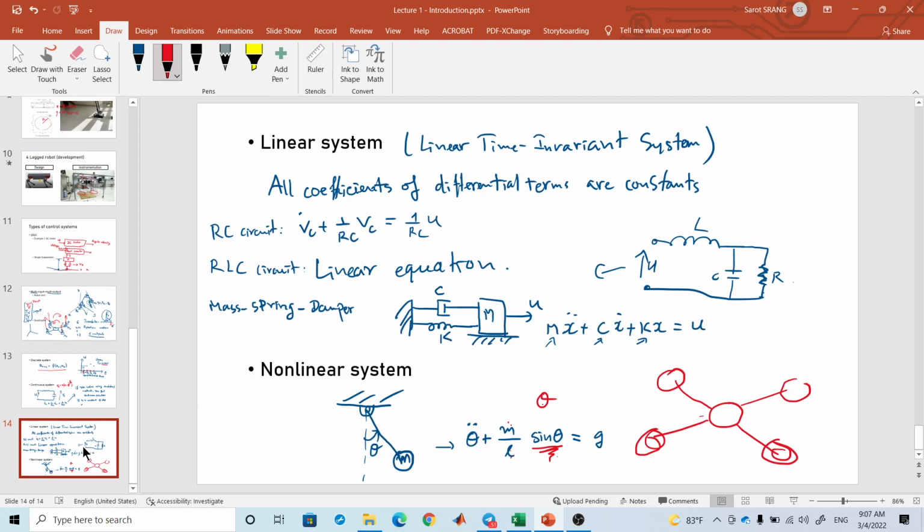Many systems, even the commercial aircraft. The equation of motion in 3D has 12 equations, 6 for translation, 6 for rotation, very highly nonlinear, but you can do the linearization and look at the relationship of a single input to a single output directly.